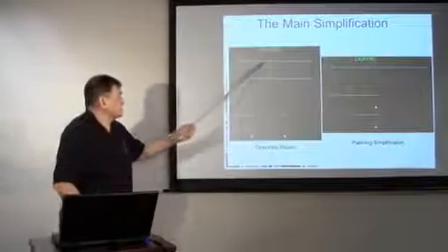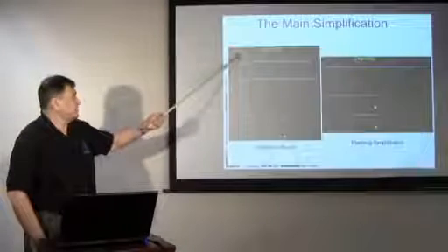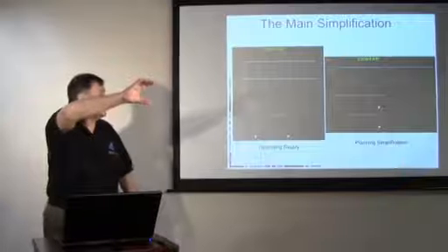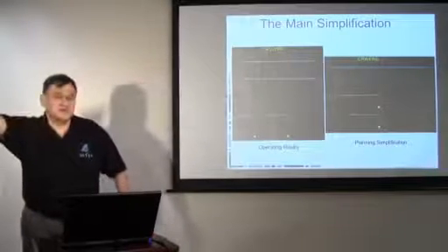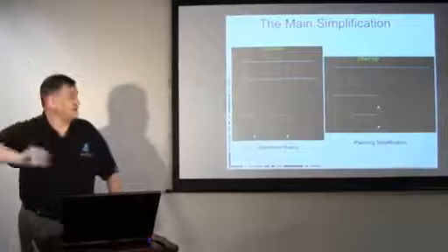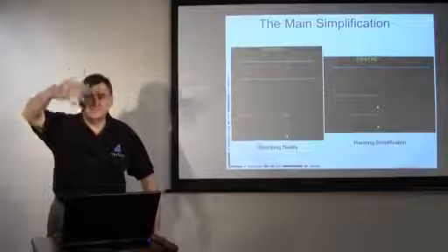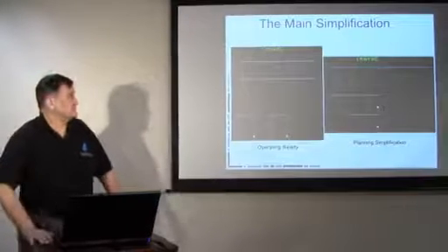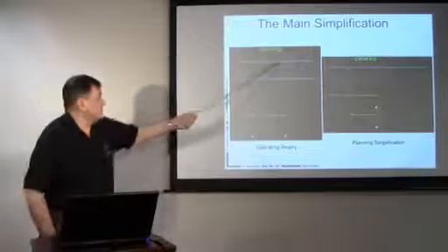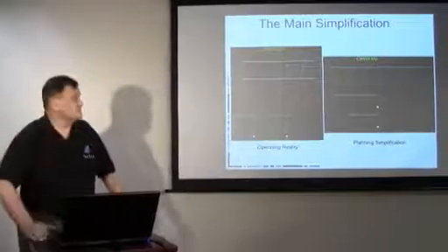This is something that the system operator can relate to. He's been in the substation. He can actually recognize a bus section, which is 3 conductors, solid conductors, typically copper, which are actually 1 for each phase, A, B, and C. And then, of course, we've got the circuit breakers, which are huge air blast or SF6 or even oil tanks. So an operator can look at this diagram and be very clear. Well, that's breaker 5. I know that. I can see that in the substation.